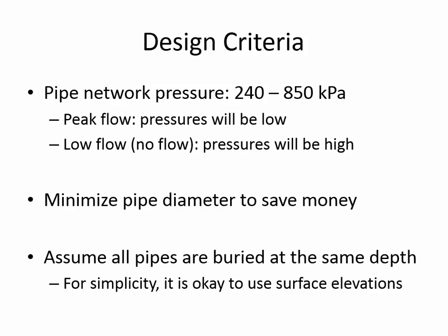There's actually several different ways within WaterGems to say, here's where the water is coming from. You can tell WaterGems that the water is coming in through a pump, or there are tanks, but the symbol that I think is simplest to use is reservoir. You'll click on a location, and then type in the elevation of the reservoir, which is the water surface elevation. That water surface elevation won't go up or down in the mind of WaterGems. It's just where the water level is during this peak design condition.